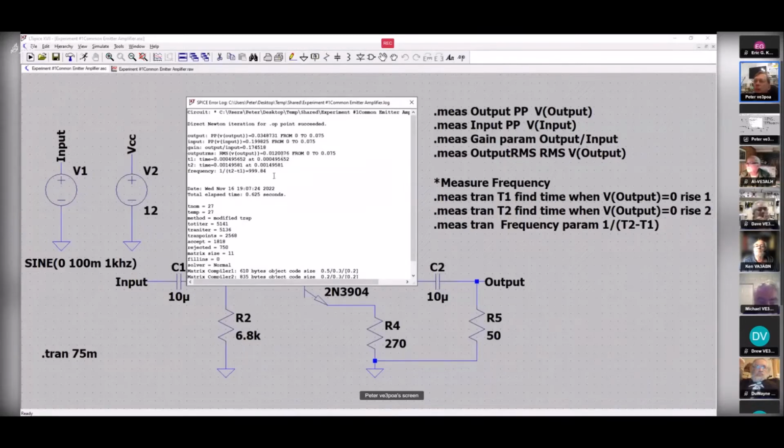that point, I noticed here, for example, I'm telling SPICE to do a 1 kilohertz sine wave, and it's 999 point something, so it's not quite there, close enough. And same thing with some of the voltages. They're just off ever so slightly. So I'm thinking, and I haven't done it yet, and I'm not 100% sure how to do it, I have to do some reading and searching, but delay the start of when it makes its measurements. I'm thinking that way the waveform settles down a bit, and that might make it a little bit more accurate.